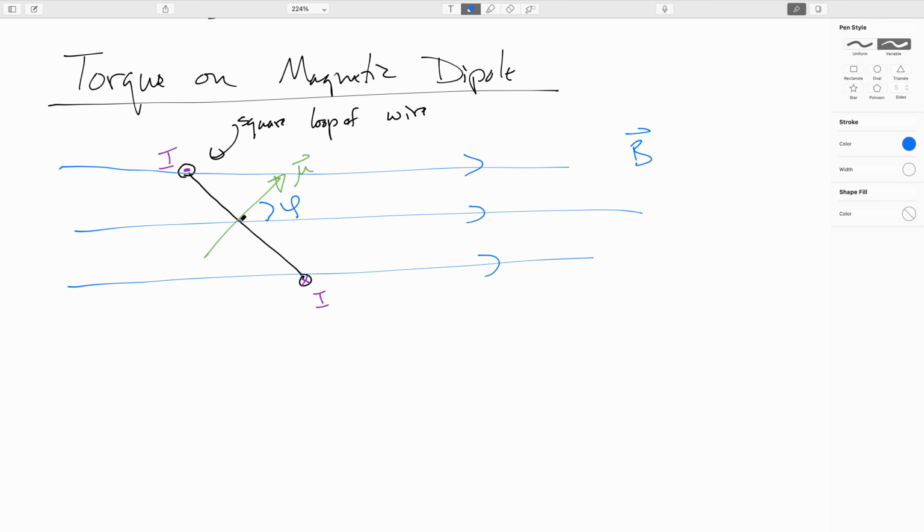Okay, so go ahead and do some right-hand rule action and figure out the directions of the magnetic forces on the top and the bottom part of the windings here. Okay, so for this one, you should be pointing the index finger of your right hand out of the screen. Rotate your hand around your index finger until your field fingers point to the right. That might start to take a little bit of gymnastics to make it happen, but you can make it happen.